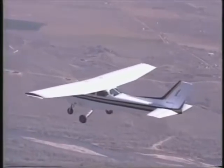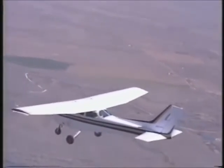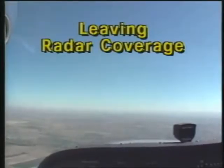When you leave the radar coverage area, the controller will let you know that the service is no longer being provided and will have you reset your transponder for VFR flight. Cessna 740, radar service terminated. Resume your own navigation, squawk 1200.